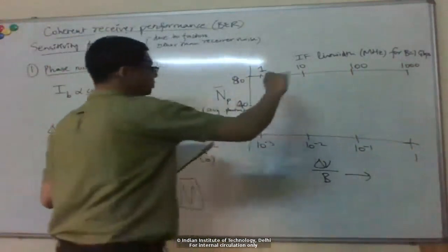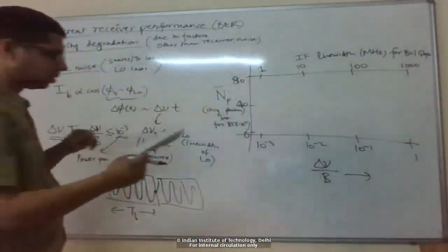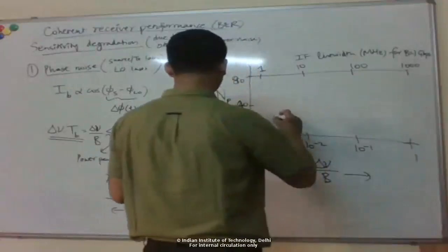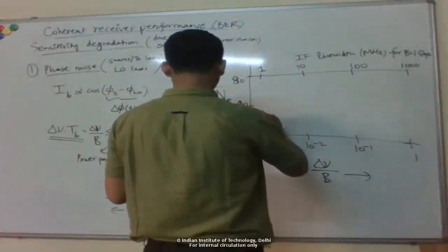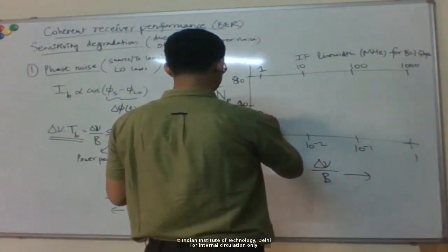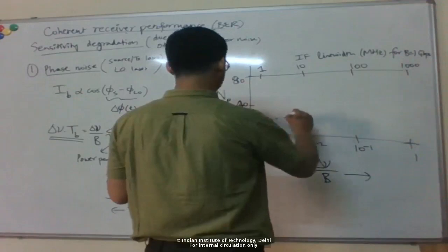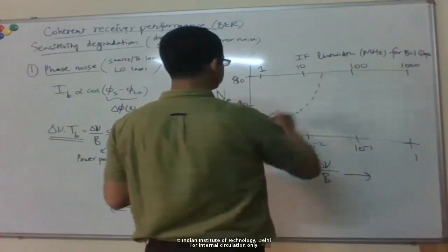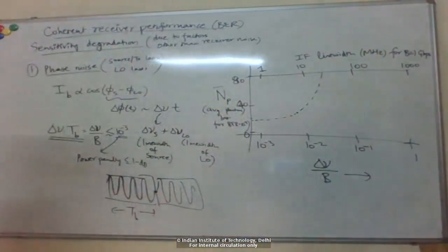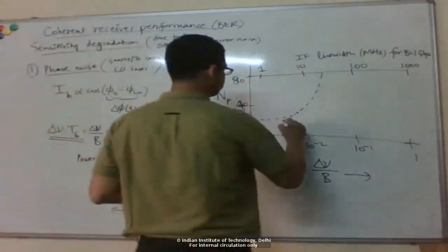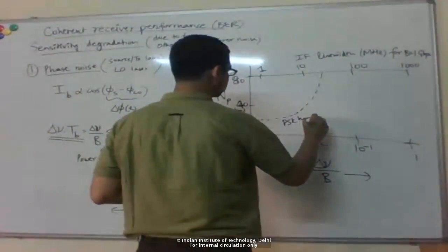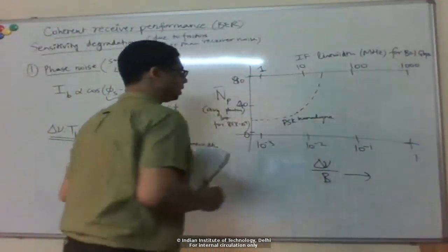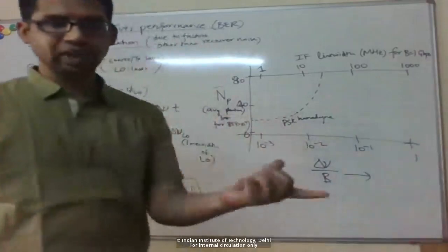So again, we get different curves for different modulation formats. We won't go into the details of the calculations, but to see how they vary. So if you look at the best in terms of sensitivity that we got, it was the PSK homodyne. So that goes like this, but it also scales the worst with phase noise because in PSK homodyne, basically we are encoding information in the phase, right?